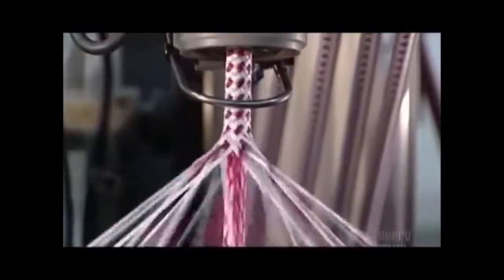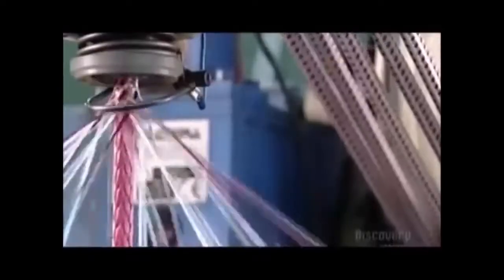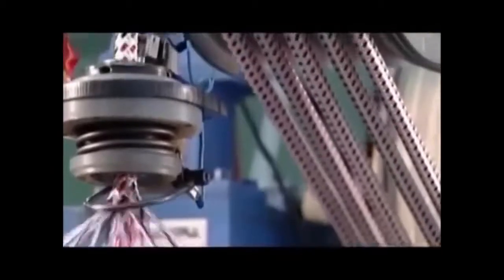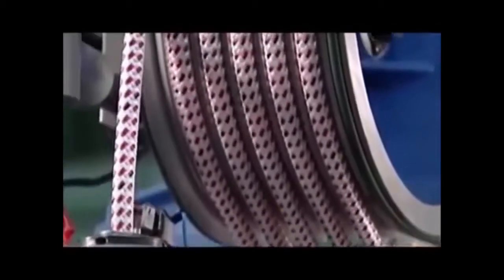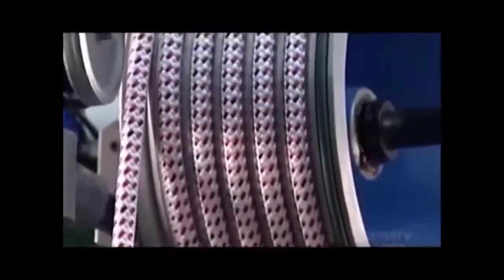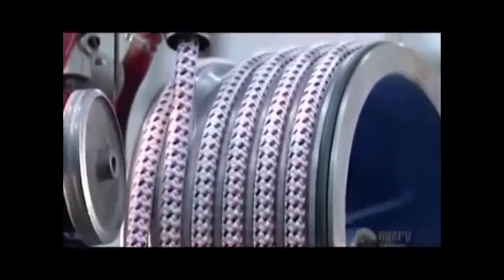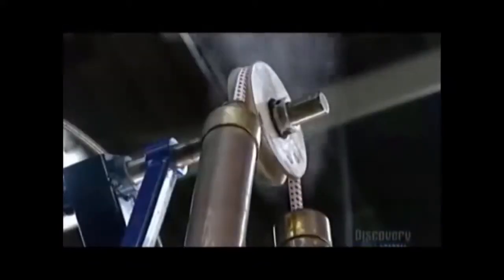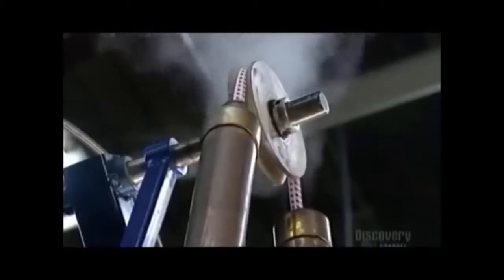Now another maypole braider weaves a synthetic rope that's stronger than steel, yet lightweight and flexible. That's because the strands at the core are braided with a material called ultra-high molecular weight polyethylene. It's a high-performance thermoplastic. This rope will be used for advanced yachting. A pulley draws this high-tech rope through some metal pipes filled with steam. This shrinks the polyester jacket around the powerful core for a tight fit.